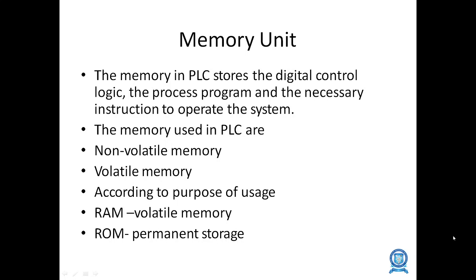Memory unit. Memory unit in PLC stores the digital control logic, the process program and necessary instruction to operate the system. The memory used in PLC are non-volatile memory, volatile memory. According to the purpose of usage, RAM and ROM are also used, which is volatile and permanent storage.